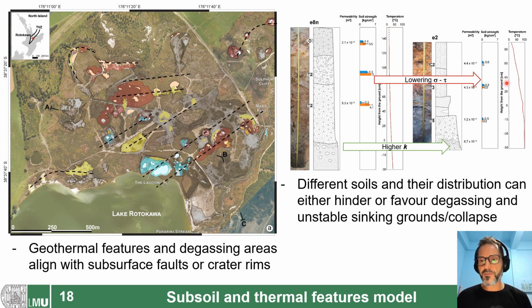This can justify the presence of thermal anomalies around this kind of site, or, as we remember from the case discussed before, the presence of this layer between other material of lower permeability can allow the fluids to move horizontally and produce a sort of thermal anomaly in the vertical profile, or thermal bulges.